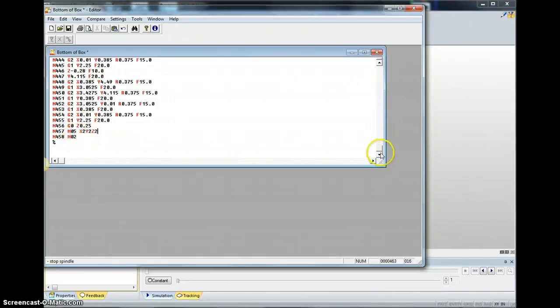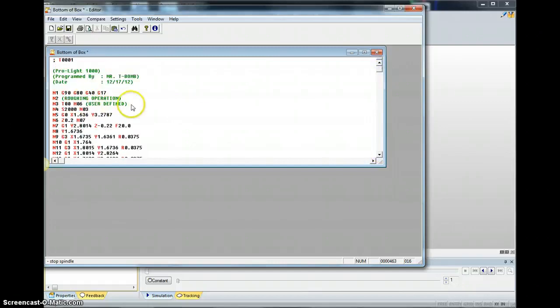So once you've done those things, you've added that in there, you've gotten rid of this piece, check your spindle speed, then you can save it, save the code, name it something, okay, so make sure you save it in a certain location, and then you can open that saved code in CNC, and it should be all ready to go. This is the one piece that you might need to change, is G17. If you did some parallel lacing, but we can talk about that. If you have an issue, if it says K code invalid, you're going to have an issue with this G17. You'll just need to change that to either G18 or G19. So hopefully that will get you going with Edgecam.